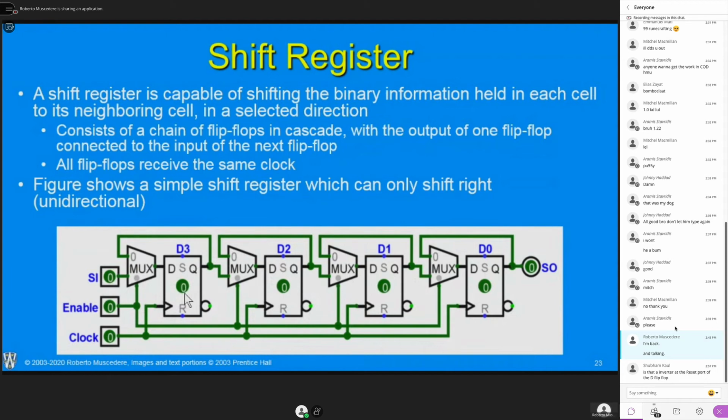A lot of information can be sent serially like this. So the connection between, let's say, this shift register and another shift register could be kilometers away. If we send the information 1 bit at a time, it actually becomes quite reliable. In fact, I believe I discussed this at some point before, but mostly any way we transmit data today is done serially, because it eliminates a lot of the noise problems that would normally affect parallel circuits.